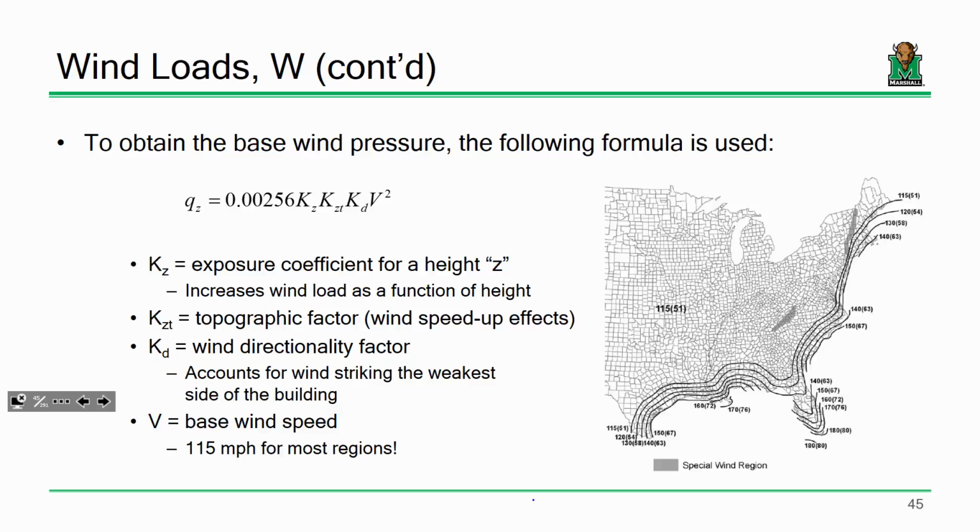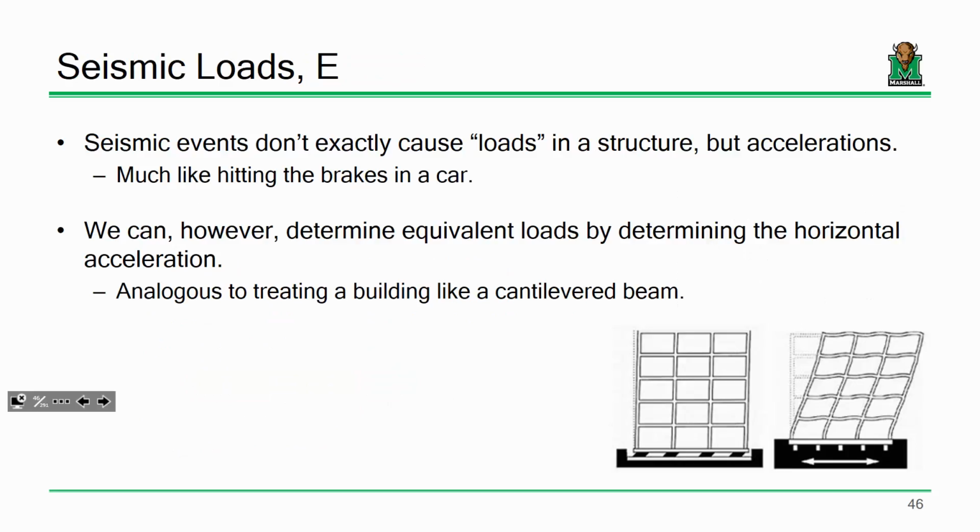So you all remember Bernoulli's equation, you have point 1 and point 2. You set your elevation heads equal so they cancel, and solve for the pressure under a given velocity, and then throw a unit conversion in there to convert velocity in miles per hour to a pressure in pounds per square foot, and that's what you get. So pretty straightforward stuff, and that's really what I'm going to leave it at for us in here. I just want you to have a general idea behind where the wind speed equation is coming from. It's really not that incredibly difficult to compute.